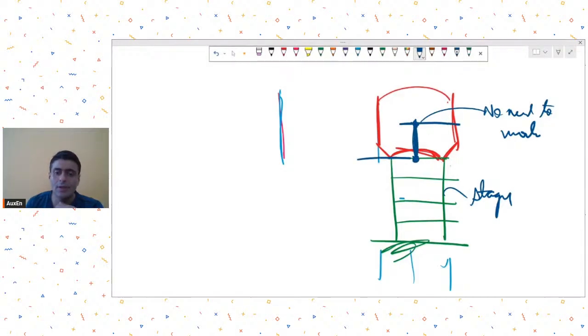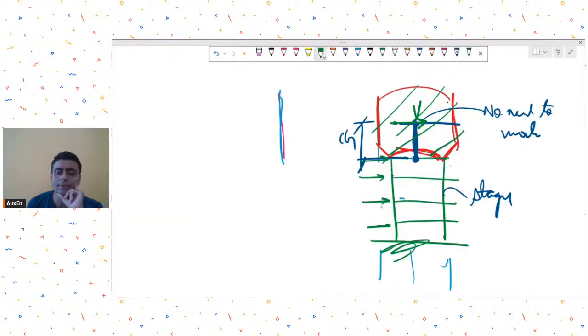This height will be the height of the CG, the distance of the CG that you have calculated. Apply the shear force at this location. This shear force will be for this tank portion. Whatever earthquake shear you have got for the tank, you apply it over here. For the staging, the software will automatically apply it at all the points, and accordingly you will get the base shear and overturning moments.